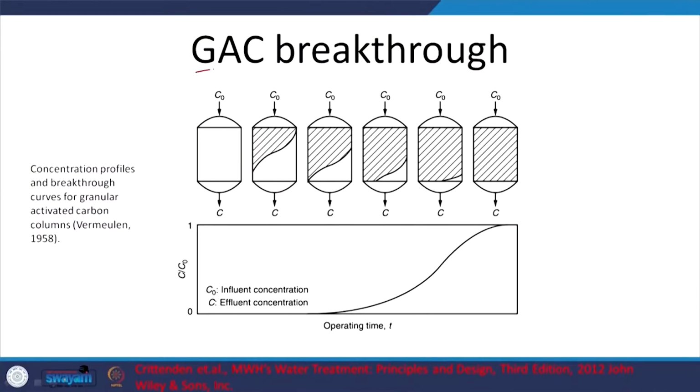In that context, obviously, activated carbon has some active sites which can adsorb my organic compounds of interest, right? And after all these sites have been exhausted, I need to replace the relevant activated carbon. In that context, I believe we looked at breakthrough, right? Granular activated carbon and breakthrough, right? So, this is the mass transfer zone here, and I guess here it is the mass transfer zone here, and so on and so forth.